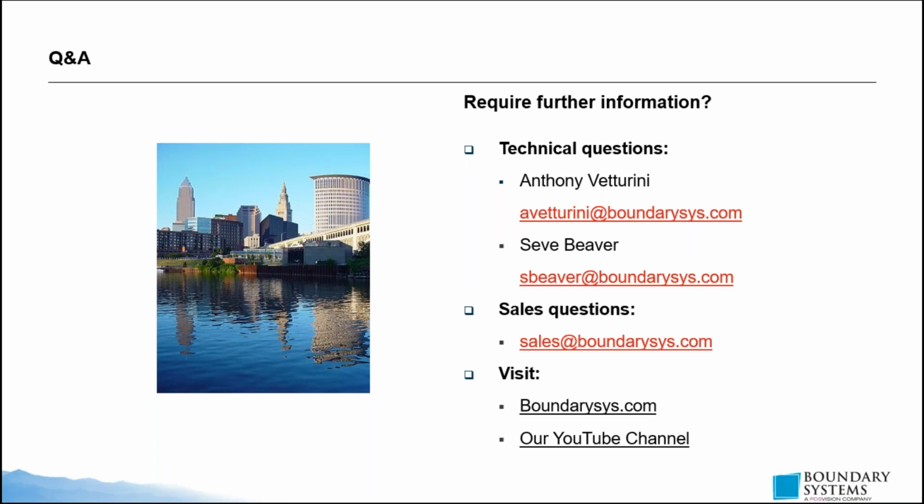So for example, some of the additions are that in one single part, I can have 3 or 4 bodies, right? And design in the context of a part, and eventually when I want to break it off into an assembly, I can pick on body 1, right click and say create new part. Pick on body 2, right click, create new part, and do the same for all the different individual parts.